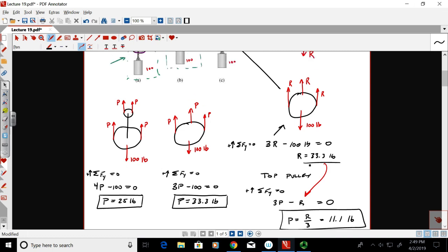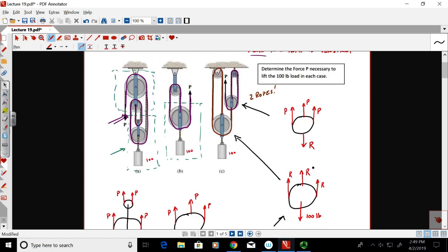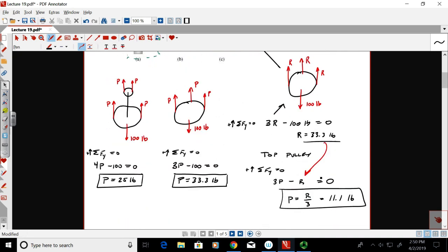Now, this almost feels like you're cheating when you first learn about this 9-to-1 pulley like this. It almost feels like you're cheating because it feels like, wow, I could actually get that much force. Okay? But you are paying a price when you use a pulley system. Okay? You say, well, what price am I paying? Well, let's say you wanted to lift the front end of a car, right? And let's say you want to lift the front end of the car maybe 10 inches. Okay, you hook this onto the front end of the car, and you figured out that if I can get an 800-pound force at the front end of the car, I can lift it.